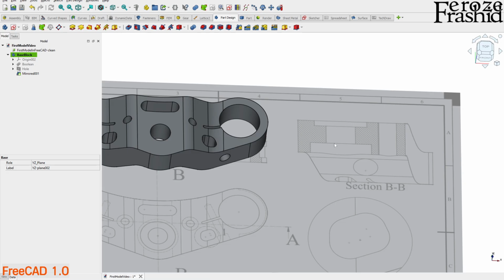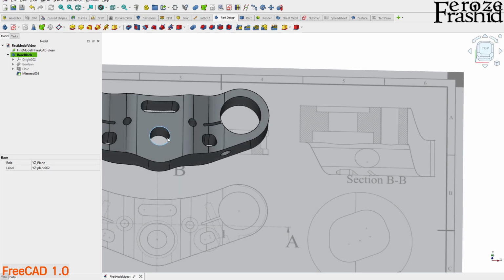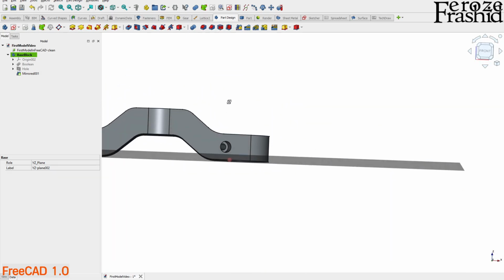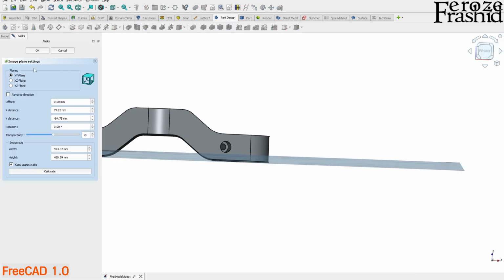So I'll have to draw this sketch in the middle. Luckily, we have the origin right at the center of this circle, so it would be easy for us. Let's do that. I want to draw half of this sketch so I can revolve cut on both surfaces at the same time. So I want to draw a sketch on this face, which is the XZ plane.